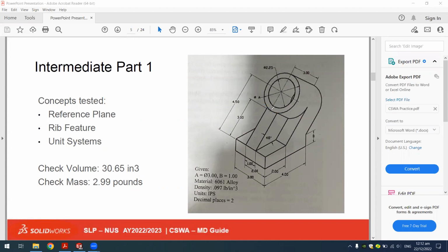Because if you draw your sketch on the mid plane over here, okay, I'll draw the front view here. Eventually, this is the arc, the front view. Your extruded feature will look something like this. Only the center point touches this arc over here, and here are all empty spaces. But if you extrude more, then this could occur. Yes, the empty spaces are filled, but here are some extra materials.